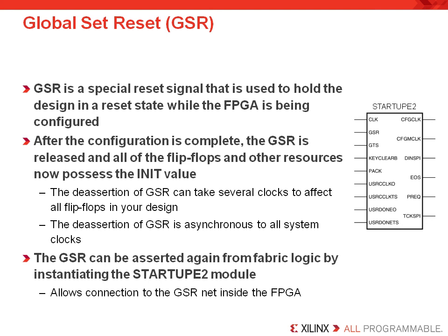But what you can do is drive another signal to the GSR port, and anytime you want to reset your system, you can drive that GSR port, and it basically acts as an OR gate to all the synchronous elements in the design on the reset port. So after configuration is complete, the GSR is released, and all the flip-flops and other resources will now possess that initial value state. The deassertion of the GSR can take several clocks to affect all flip-flops in the design, and